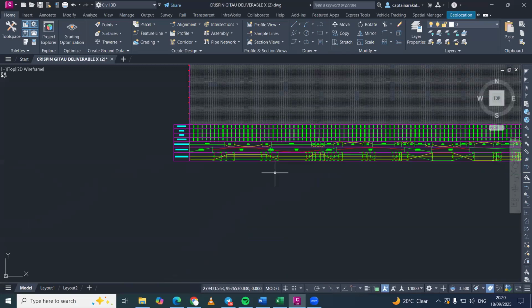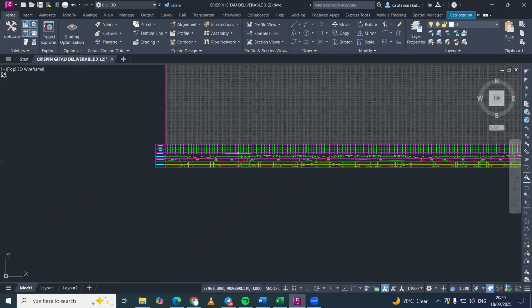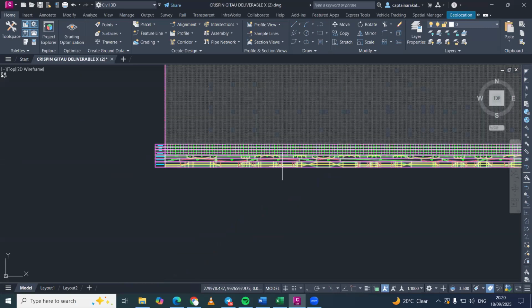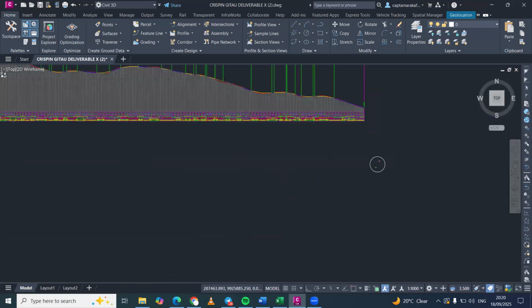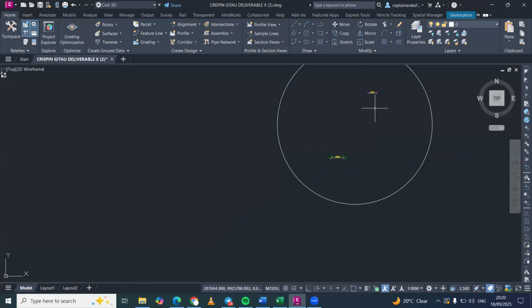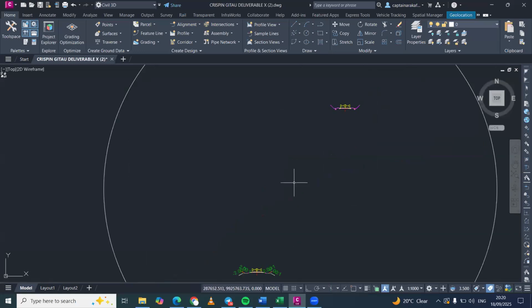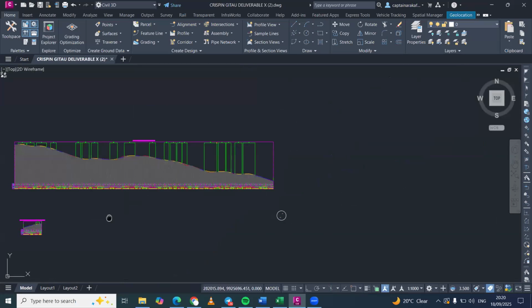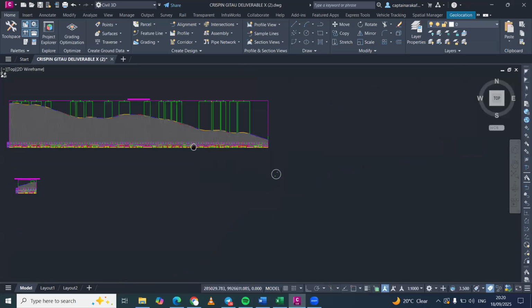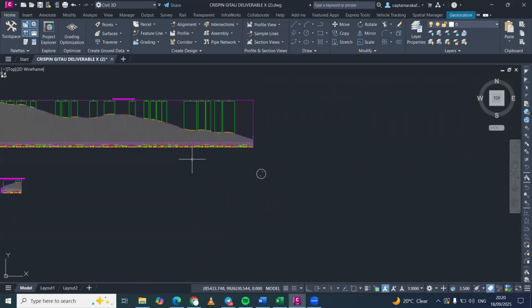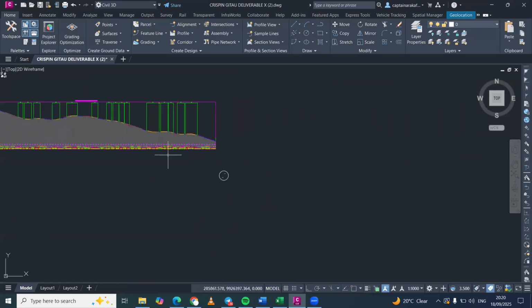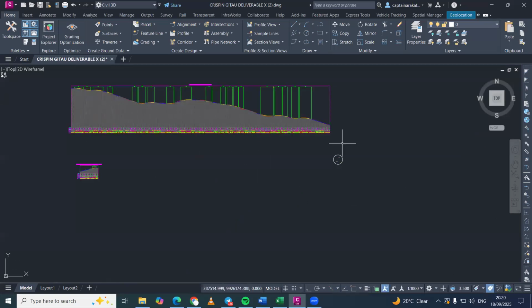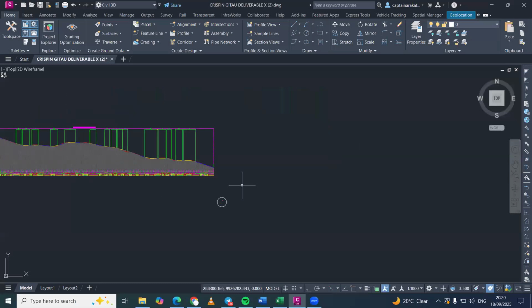We did our data bands, which is another thing that we can display during plan and production. Remember, we did our assembly, which we used to create or model our corridor, okay? Our corridor. So now that the design is complete, I want us to display our sections, just like how these other elements are displayed. And the way to do that is always through the ribbon.